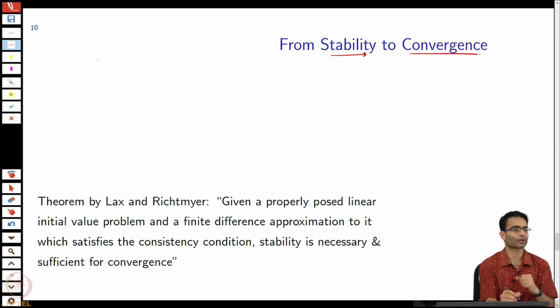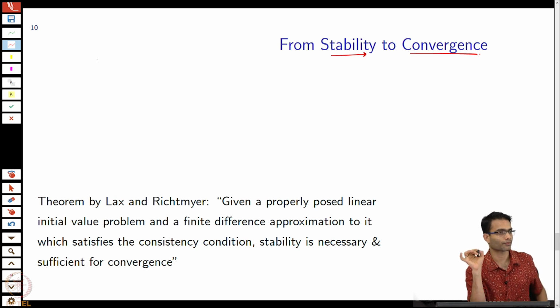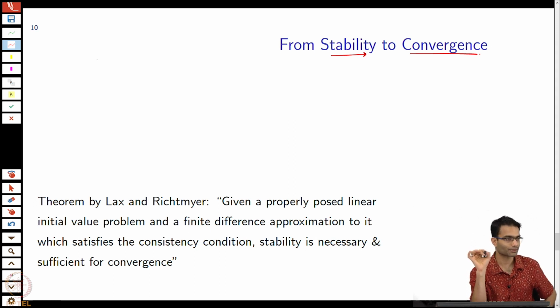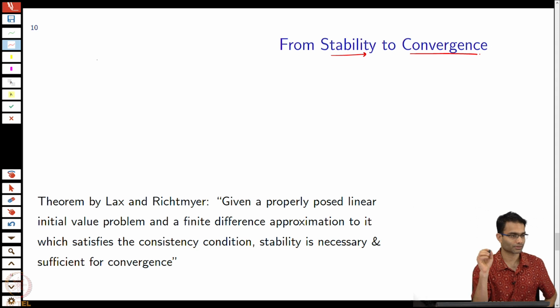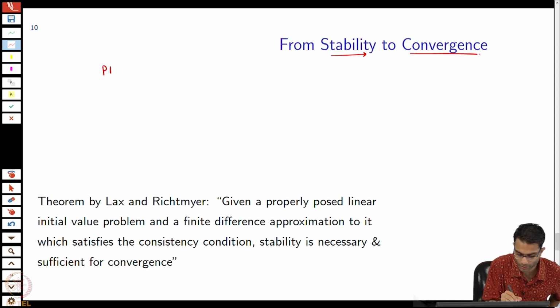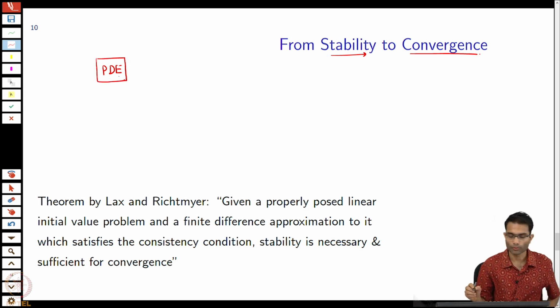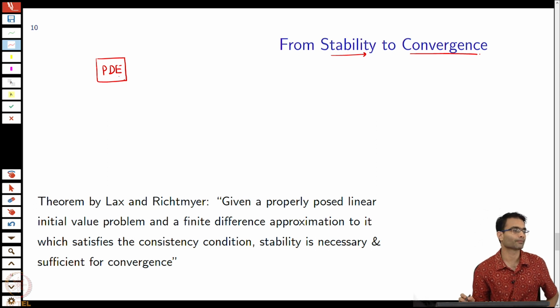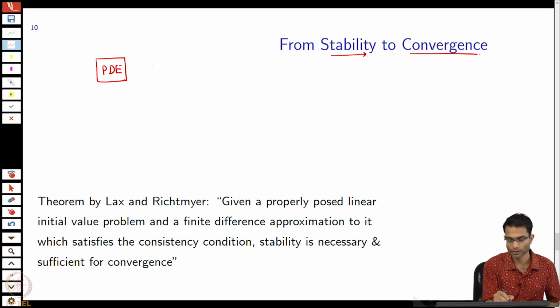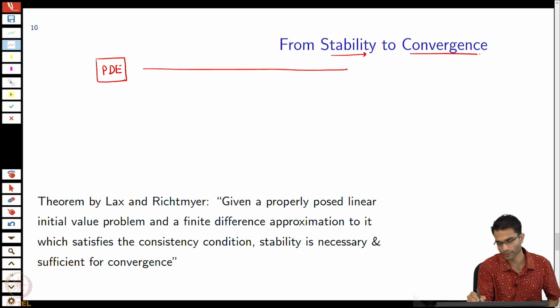What do we start with? What was our absolute starting point for FDTD? Before E cell, Maxwell's equations, i.e. partial differential equations. So, we start with a PDE or a set of PDEs. Right. What did we do to this PDE? Next we went to E cell, right. In other words, we discretized it, right. So, let us draw a long arrow over here, we discretized.